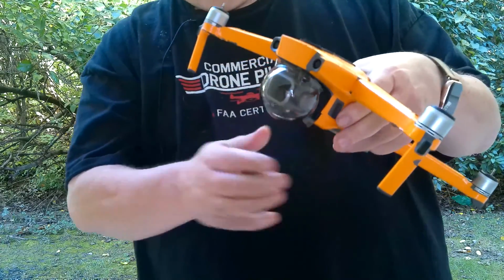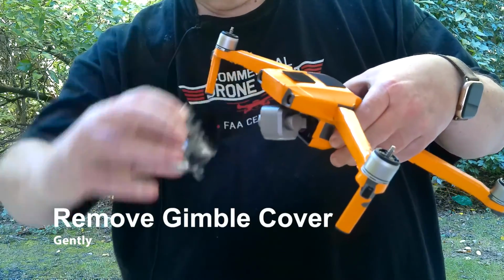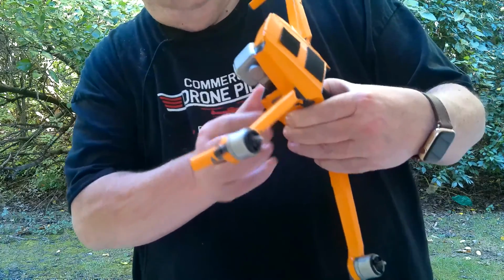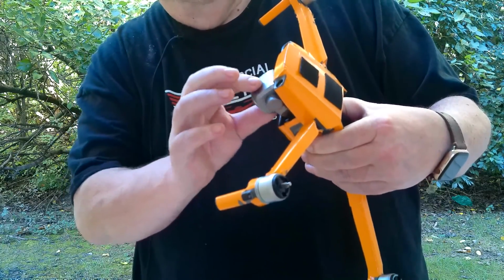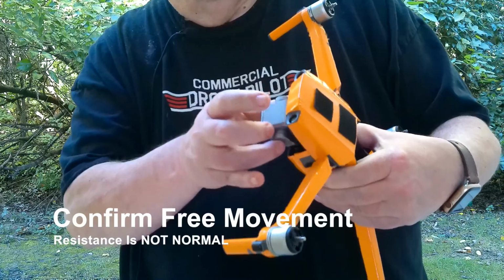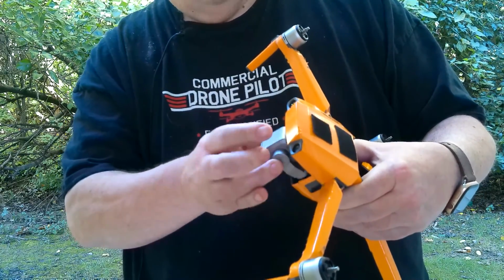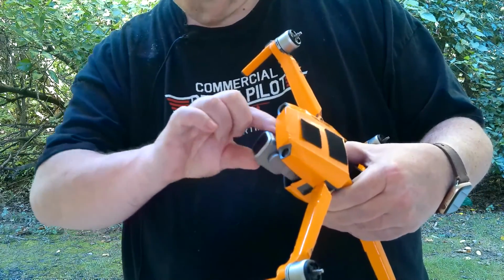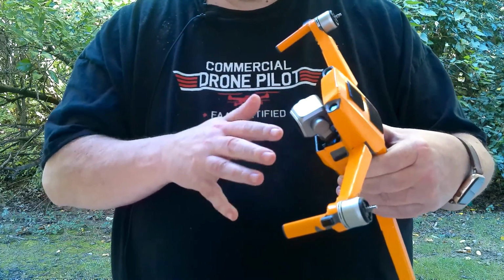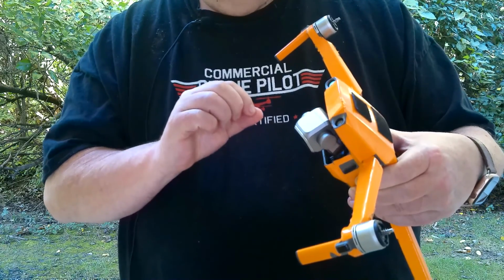So now we can carefully remove the gimbal cover. And look in the gimbal housing and just take your hand and make sure everything moves freely in all three axes. That there's no dirt or debris or anything in there that could restrict its movement or make it stick.